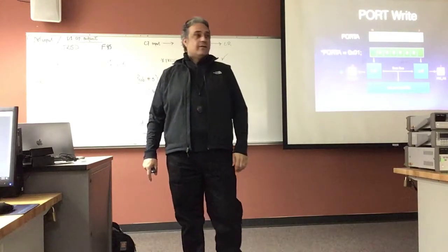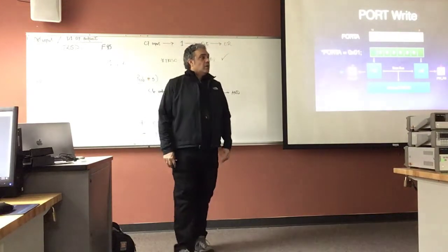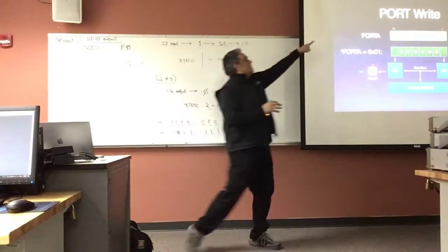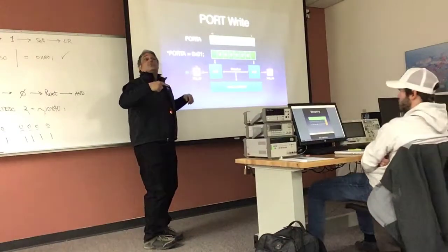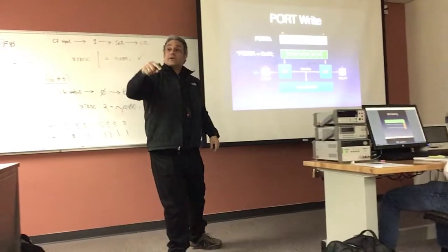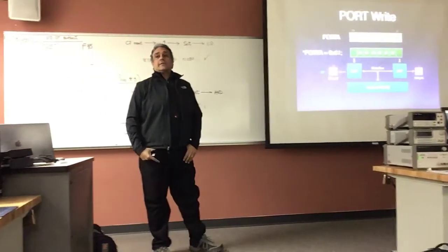The tri-state is the setup. See that? So the only way that you can do a port write is if your tri-state was set up as an output first. Does that make sense?